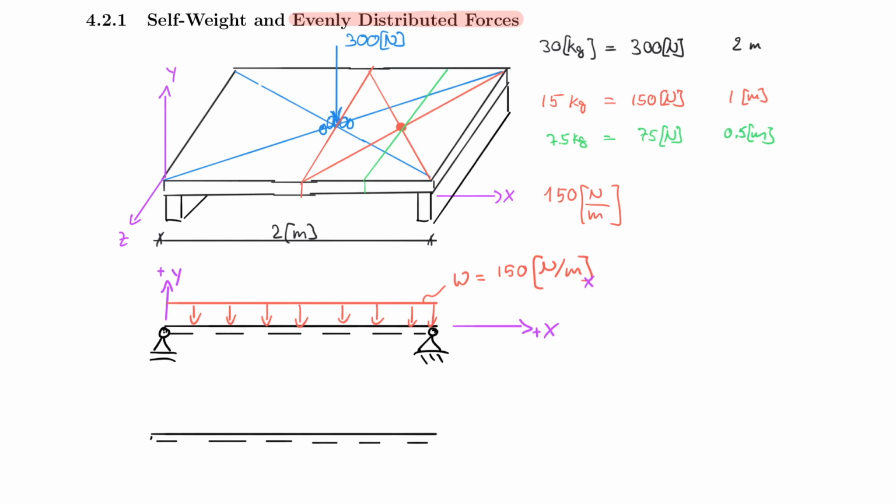Before I do that, I of course have to bring my support reactions down here, and then I can go ahead and actually lump the force into the single location where you originally placed your hand. So it's acting in this place here at 1 meter, at x equal to 1 meter, and we call that F. I often call that F resultant, but really what that is the lumped force.